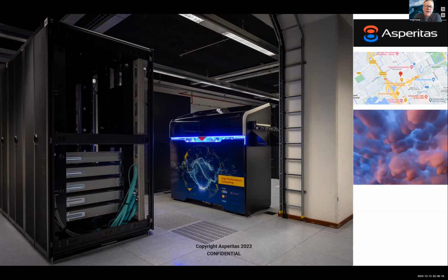But okay, great. So this is an example of an immersion cooling solution placed in the white space alongside some air-cooled racks, and it's a great illustration for HPC workloads. In this case, it's for Shell, where we're cooling equivalent workloads to what you see in those air-cooled racks in a single tank, without any load on the air cooling, and recovering 95% of the heat to liquid for heat rejection, or heat recovery to reduce the bottom line, or as you say, to give it away for free, which is nice.